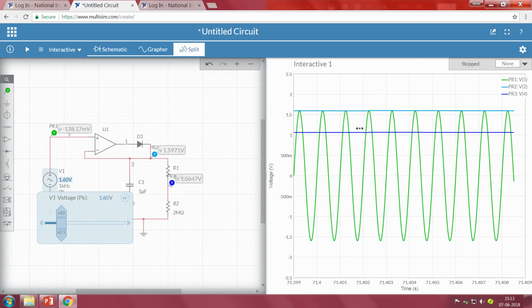A simple comparator is enough. We do not have to go with any Schmitt triggers or anything. The reason is we are not setting two thresholds here, we are using only a single threshold. If the input value is greater than this particular value, only that signal has to be passed, detected, and counted. Depending upon how many such pulses we are getting, if you use a counter there, then we can automatically see the number of pulses we are getting per second or per minute.